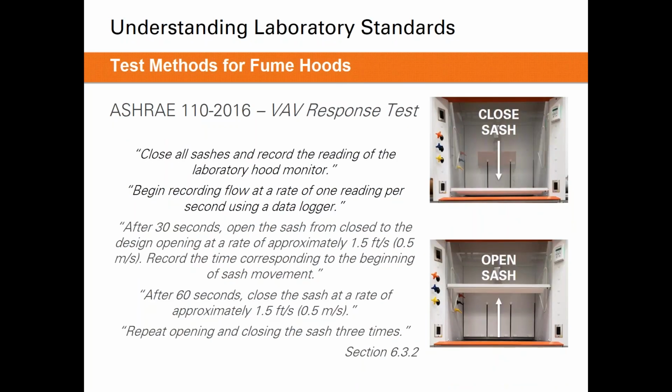The next test that we'll discuss is the VAV response test. This test is designed to understand how quickly we react to changes in the sash height. So to start the test, we'll close all of the sashes and record the reading of the laboratory hood monitor. We'll then begin recording at a rate of 1 reading per second using a data logger. And after 30 seconds of taking readings at the close position, we'll open the sash from the close to the design opening at about a rate of 1.5 feet per